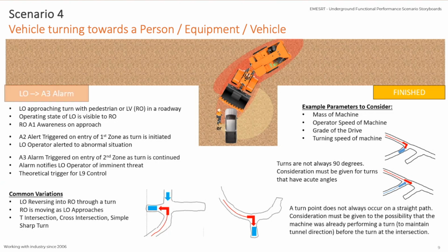And the opposite can occur too, which is the next image to the right, where we've got a gradual left turn before a full sharp right turn. And that's quite common, particularly on decline. So you might be driving down the decline in a corkscrew fashion, heading down the mine. And you might hear another vehicle coming up towards you. You need to do the opposite turn into a passing bay to allow that vehicle to pass you. So that's actually quite common, that particular example.